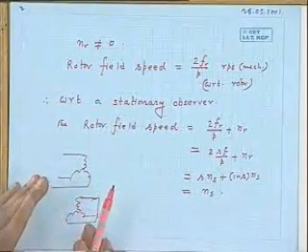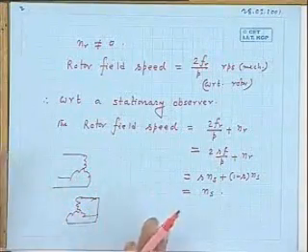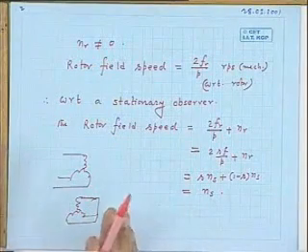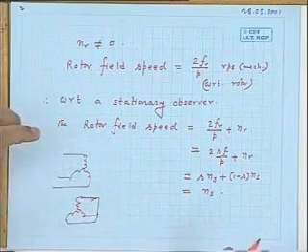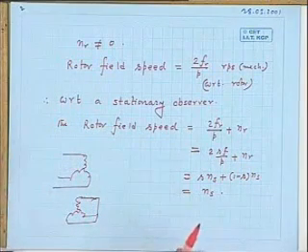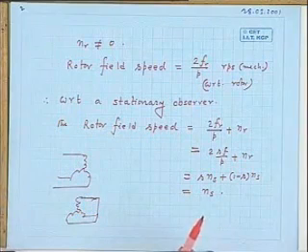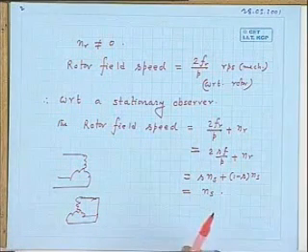The stator always reacts as if somebody has produced a rotating field rotating at speed NS with respect to the stator winding. Therefore, the stator has to always counterbalance a field moving with NS produced by the rotor, no matter what the speed of the rotor is.